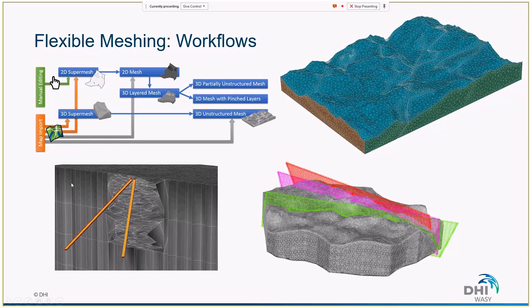So you can take the simple workflow, where you basically build your 2D super mesh. Super mesh for us means our conceptual model, where we actually indicate what the areas of interest are. Okay, we have some points because here we want to put our dewatering wells. We have polygons because these are areas of interest. Maybe we have the tailings, so we have some polygons of the pit shell projection, etc.